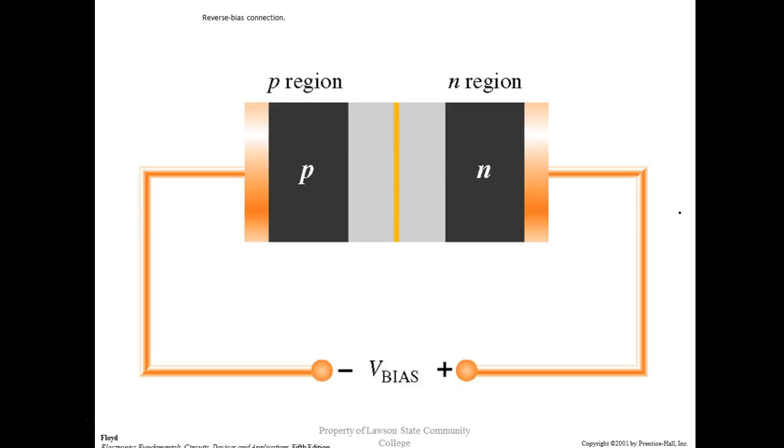So originally, when we reverse bias it, we have conduction for a really short time, not infinite. It's conduction for just a really short time, and then it stops. When it's forward bias, it conducts. When it's reverse bias, it blocks, as long as you don't exceed the breakover voltage. We can cause anything to break over, right?